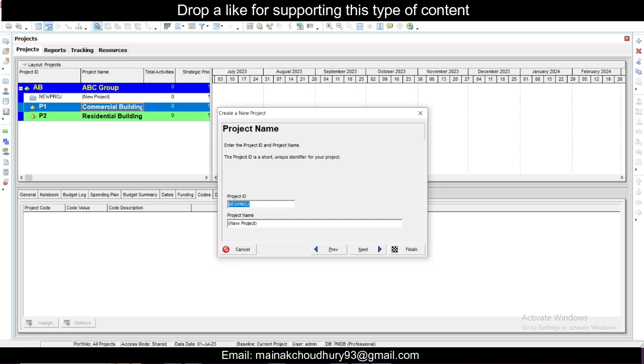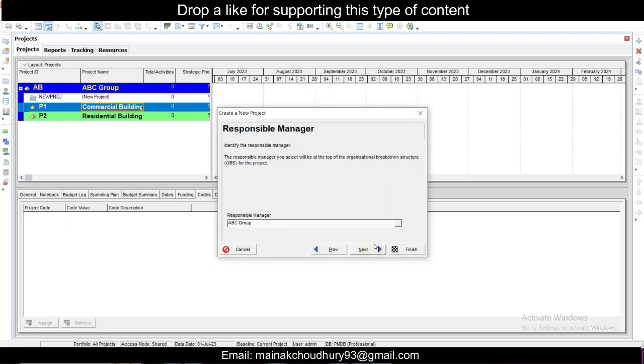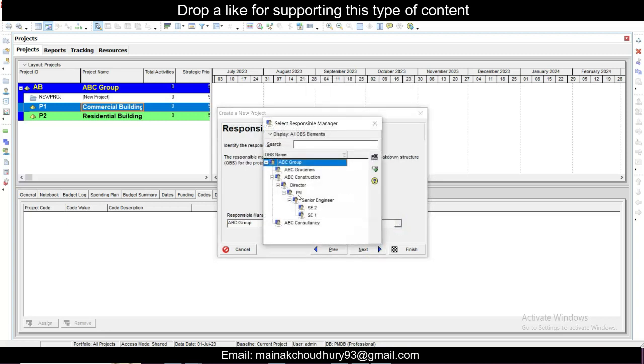So let's say P1X, give any name for the project ID, P1X. For the project name, suppose this is the commercial building, so commercial building construction is the project name. Then click on next, and you have the project planning start date. Suppose this starts from today, 1st July, and this commercial building ends on 30th December of this year. Select this, click on next, and for the responsible manager, I'll select the project manager here.